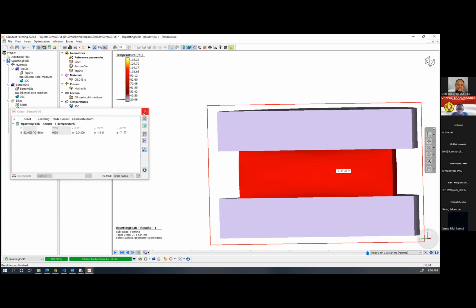But when there is a sheet metal where you want to uniformly mesh it, in that scenario we have a sheet mesh, which is again a hex element, but the meshing methodology is different for that. That's why it is separately named out. And for a hollow cylinder object, we have a ring mesh. It also gives a hex element, but the way it meshes is a different scenario. That's why we have two different types of meshing other than hex mesh.